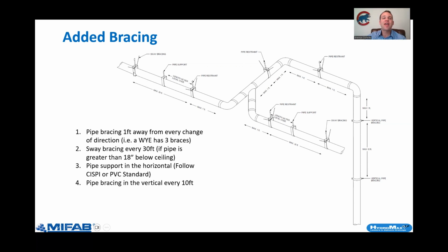We generally already have the clevis hangers there. We're just going to add stainless steel aircraft hanger cable here to make sure it's taut. The purpose is to make sure that pipe is rigid. It is not moving longitudinally or laterally.